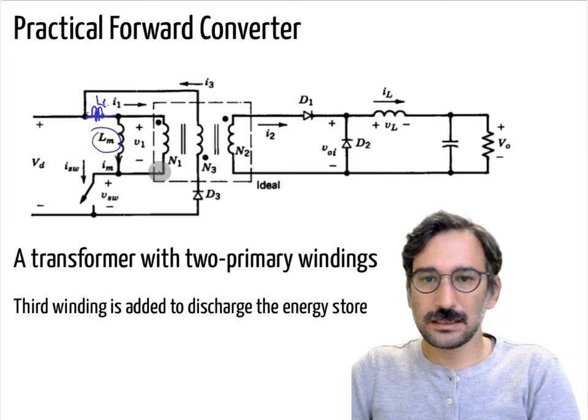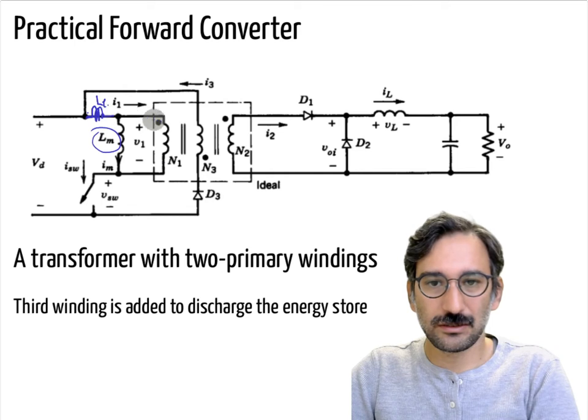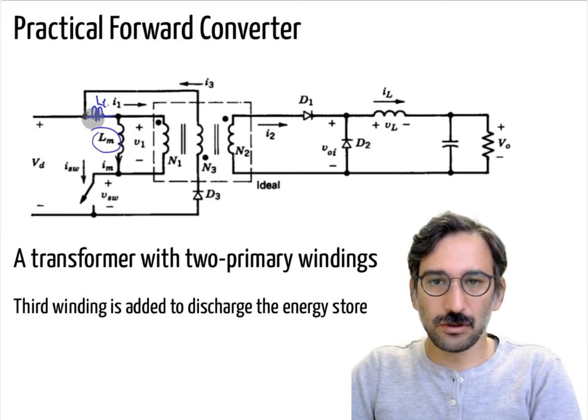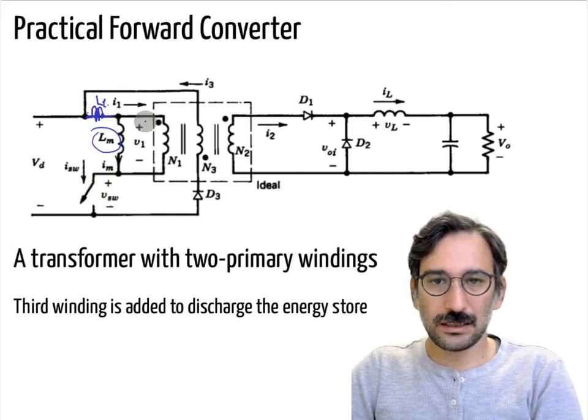That extra path, you can see it here, and we will investigate using mathematical terms, but let's have a look at how it works at first. Whenever the switch is on, you are sending power, you are charging up that inductor, right? It is the same. And whenever it is off, that current cannot flow, and that one cannot flow as well. So you have the freewheeling path.